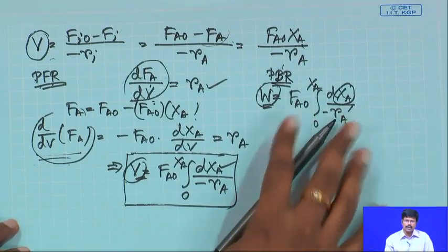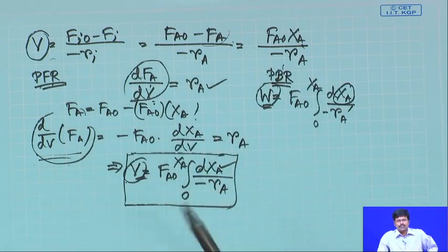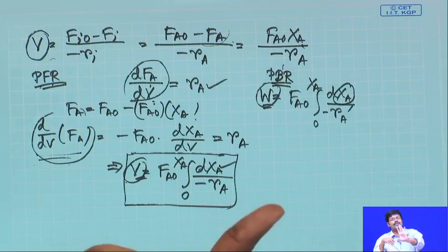So, what we have done until now is to derive the design equations in terms of the conversion, and we also gave you a concept of how to calculate the conversion. So, whatever reaction you are talking about, when you are looking at the conversion, you should look at the limiting reagent. With respect to that, you have to calculate the conversion, because if A is reacting with B, you can have two kinds of conversions that you can define.